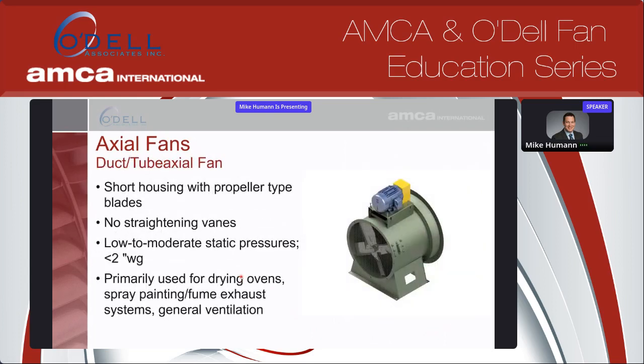So you'll see here that we also have the duct and tube axial fan. In these fans, you have a generic blade. It's more of a propeller style blade, lower cost than some of the other axial types. With a tube axial, you don't see any straightening vanes. Again, low to moderate static pressures. We're only looking at a couple inches, and a lot of applications for these are spray painting or fume exhaust systems and general ventilation.